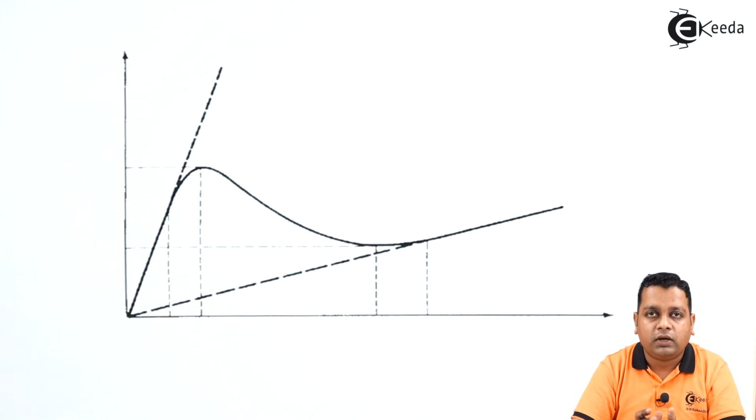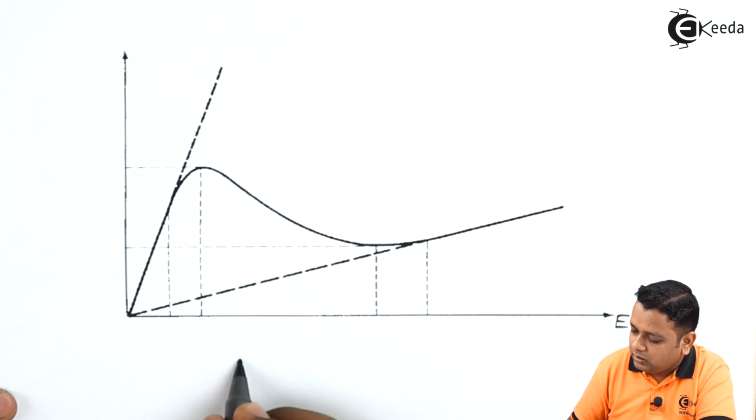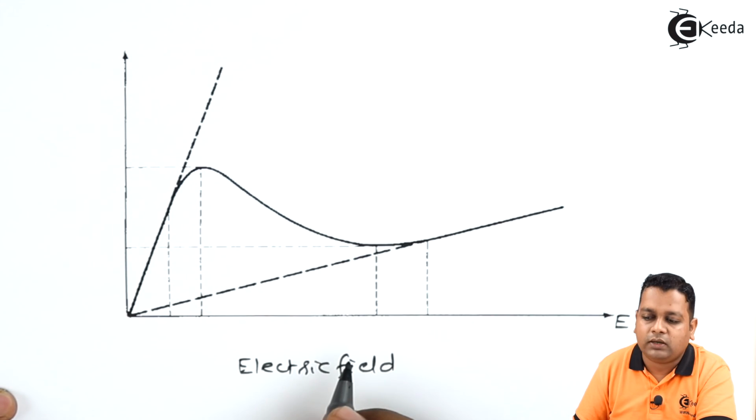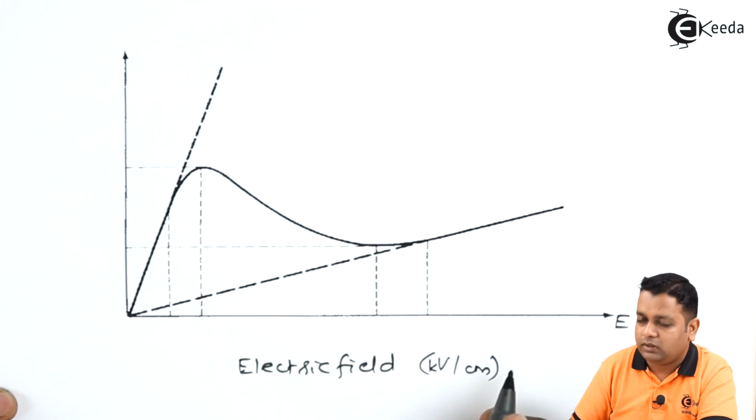So as we have shown you the characteristics of the Gunn diode according to the Gunn effect and the RWH theory, with the two axes representing the electric field and the cross-sectional current density, we can also show you the same behavior of the device by taking one axis again as the electric field and another axis representing the drift velocity. So we come to this graph. On the horizontal axis we mark E. This is our electric field, expressed in kilovolts per centimeter.